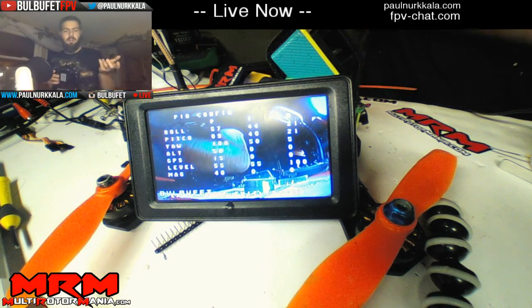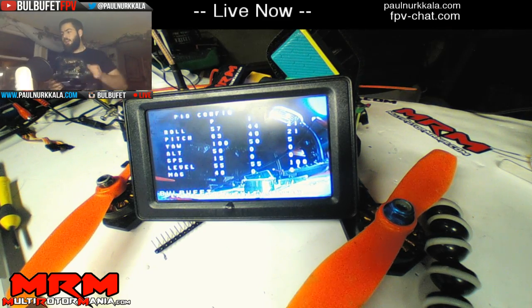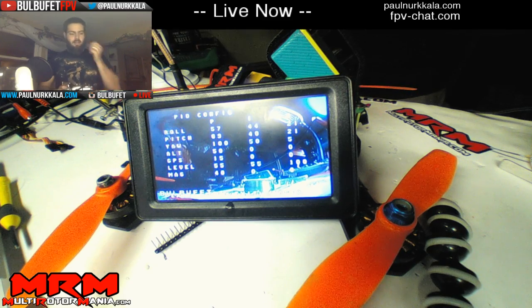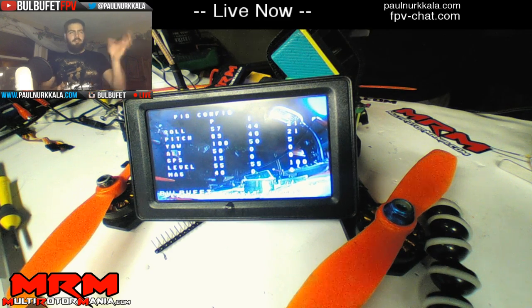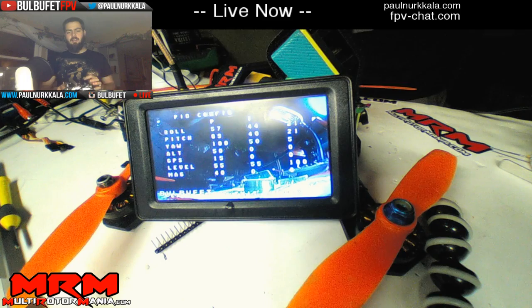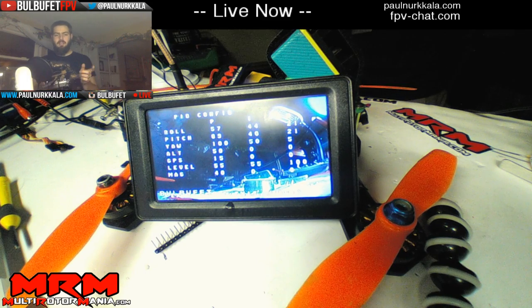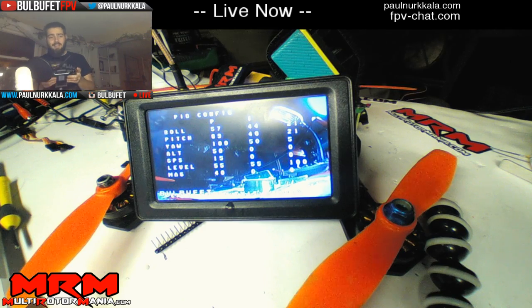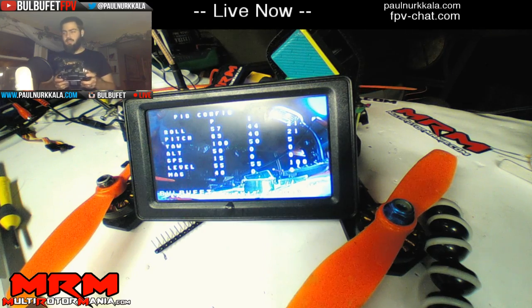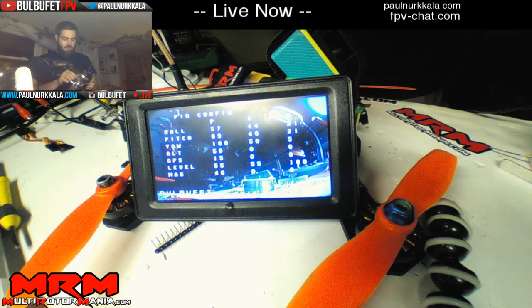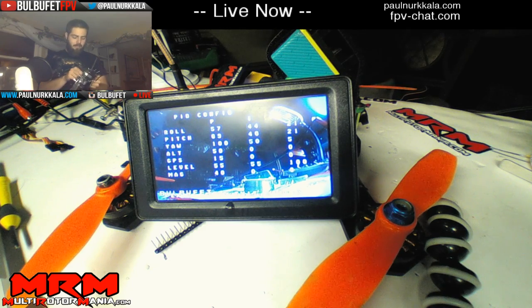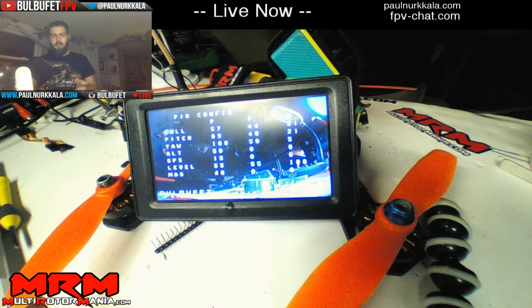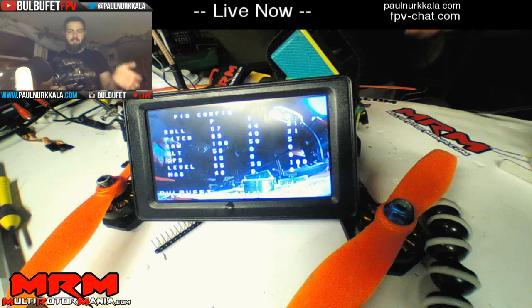So when I'm tuning this, I literally just sit down on my flight chair and plug in the quad, make a couple tweaks to the PIDs, save, take off, fly it around a little bit, come back, don't even take off my goggles, use the stick command, get back into the OSD, make things. That feature is so ridiculously nice as someone that flies a lot of different quads at different times, whether I'm tuning something of my own or helping someone else tune something, or working on a live stream build or something like that.